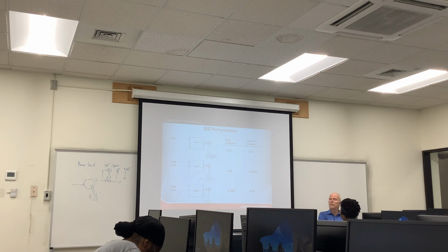And so that reduces your failure on demand probability, but it doubles your false shutdown probability. So then you say, well, maybe I should have made them 2 out of 2 voting, so they both have to tell me. And that reduces the false shutdown rate, but the failure on demand is twice as big, because they both have to be working for that to shut you down.